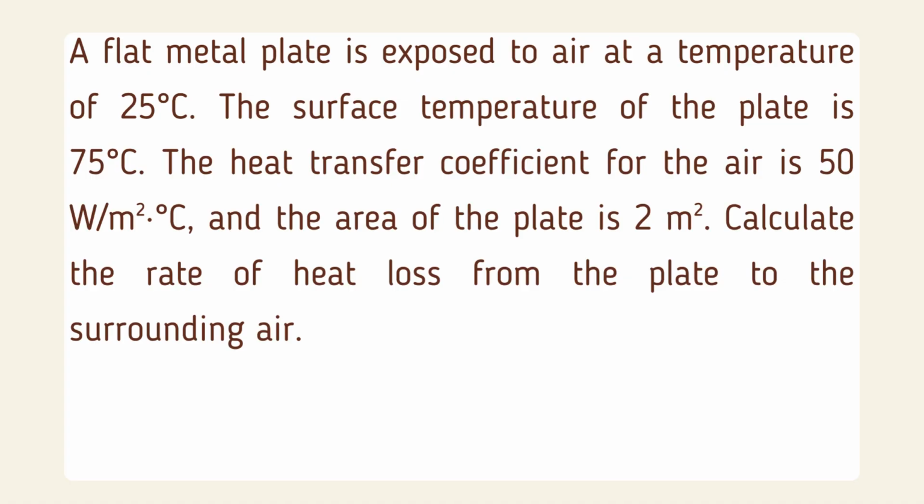A flat metal plate is exposed to air at a temperature of 25 degrees Celsius. The surface temperature of the plate is 75 degrees Celsius. The heat transfer coefficient for the air is 50 watts per square meter degrees Celsius, and the area of the plate is 2 square meters. Calculate the rate of heat loss from the plate to the surrounding air.